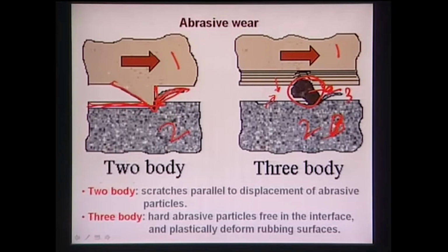These wear particles are called body 3. In a loaded contact, when one body is in relative motion with respect to the other body, these wear particles contribute to friction and wear. These wear particles are typically hard abrasive particles, and they can either be intentionally introduced between the two bodies, or be self generated during the wear experiments themselves.